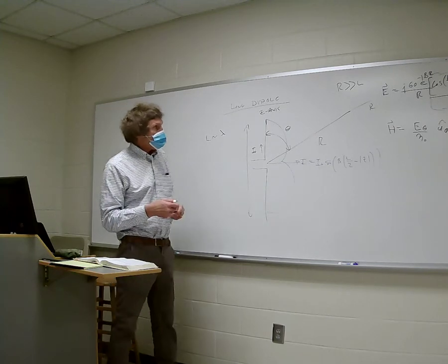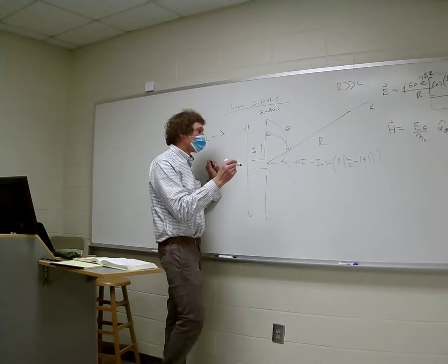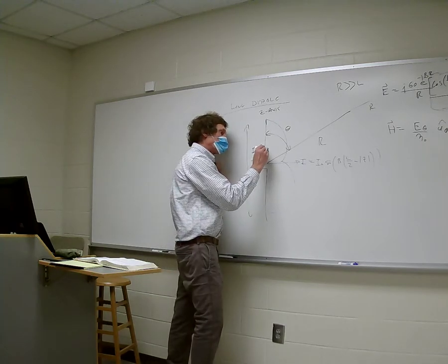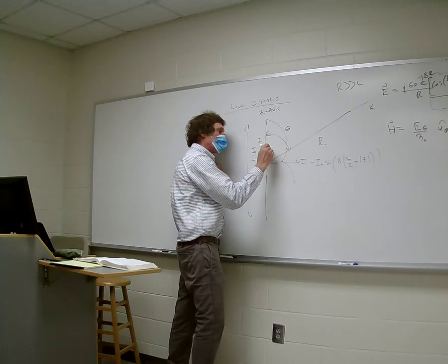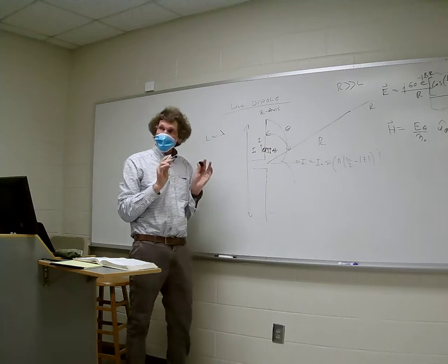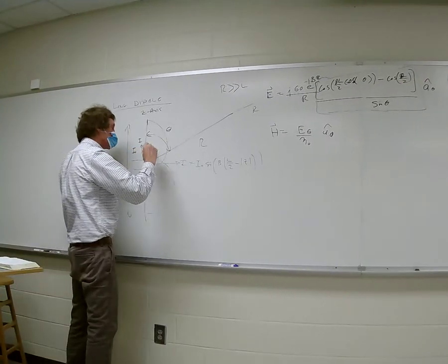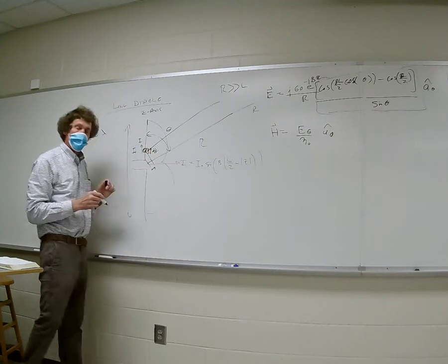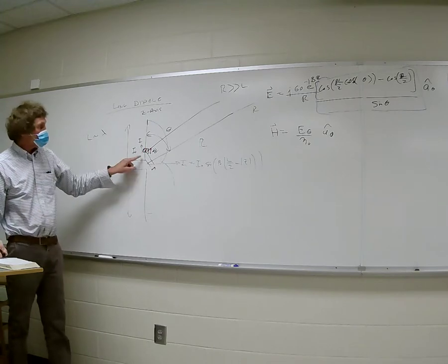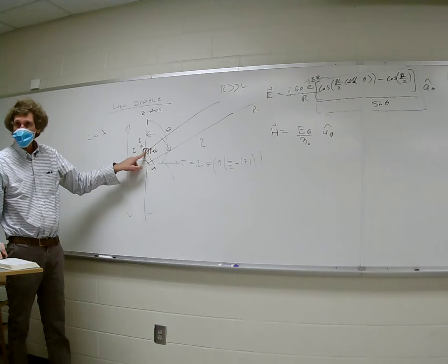Normally, if we wanted to calculate that electric field from this dipole, what we do is we take an infinitesimal chunk of current right here, I, we put a length dz, just listen, don't write, okay? We go ahead and we assume that these rays are about parallel. There would be a slight difference in the length right here. We calculate the differential electric field from this differential current. Do you all follow me? This is the way you always do this. It's the building block approach.